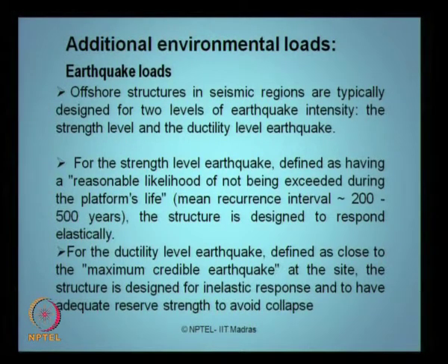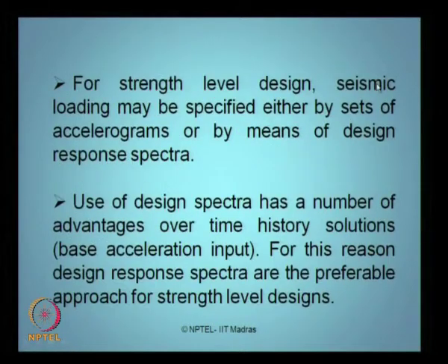You can also have the other level of design, what we call the ductility level earthquake. The ductility level earthquake is defined as close to the maximum credible earthquake, which we call in literature MCE. The structure is designed for inelastic response and to have adequate reserve strength to avoid collapse under this action of forces.